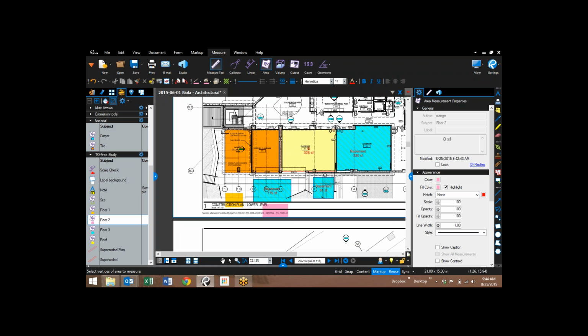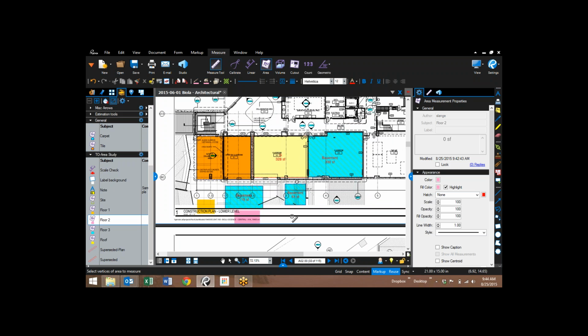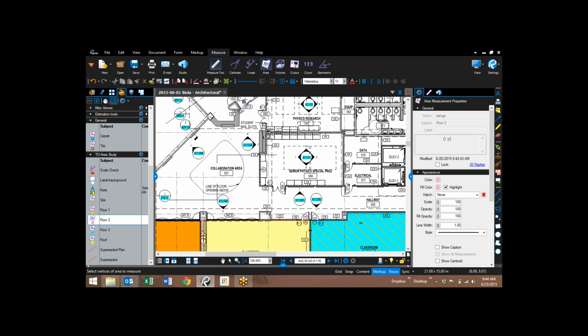And so let's go ahead and let's do a perimeter markup real quick. So under the measure tab, since we don't have one that's linear, so like a wall, let's do one for a drywall partition. So since we don't have one yet on here, let's come under the measure menu and then linear. And I'm going to use perimeter.